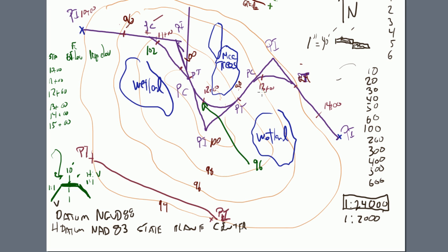Put in your major stations. Put the elevation on your major stations. Guess at what your proposed elevations will be. Make a table. And finally make sure that you have some idea to start of what your most likely proposed cross-section looks like. Thanks for listening.